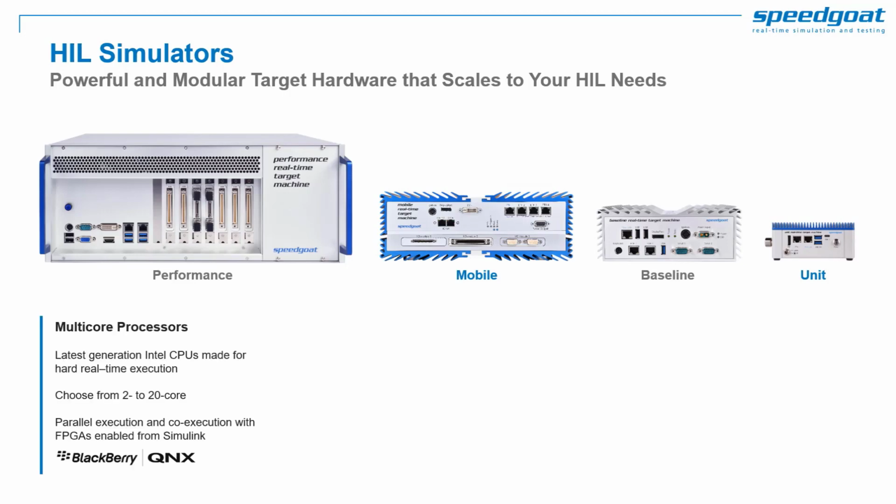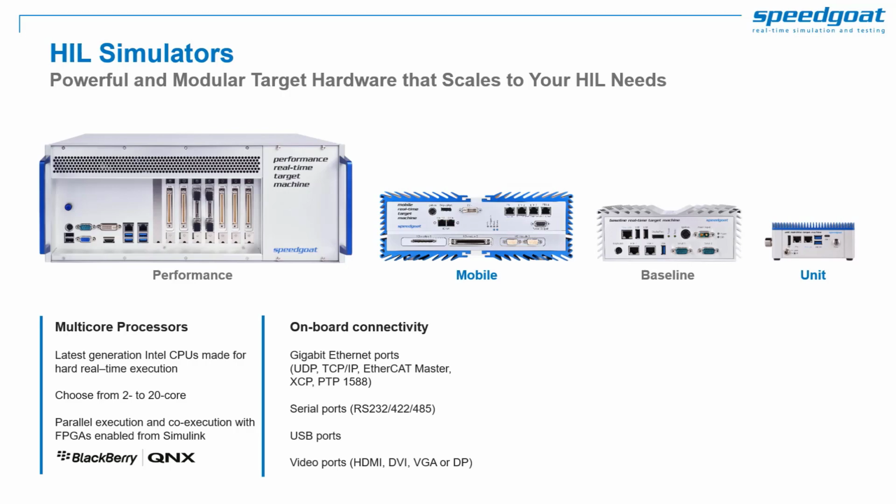Speedgoat target computers come with multicore processors, supporting concurrent execution and co-simulation with FPGAs. They run a QNX-based real-time operating system that supports certification with high-integrity safety standards. There's also extensive onboard connectivity, including a varied set of Ethernet-based protocols, serial, and video interfaces.